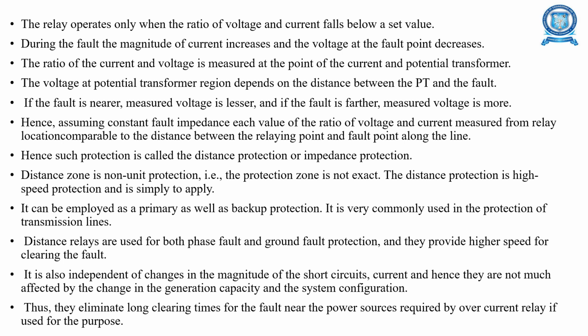The distance zone is a non-unit protection. Distance protection is high speed protection and simple to apply. Distance relays are used for both phase fault and ground fault protection, and they provide higher speed for clearing the fault. So they eliminate the long clearing times of faults near the power source required by overcurrent relays if used for the purpose.